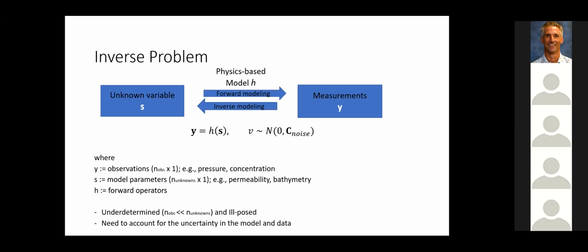And the data itself, the gauges have some observation error and other kinds of errors, and you have to account for uncertainty. So in the statistical, or stochastic, inverse problem, you have to provide not only the best estimate of the state S, but also the range of S, or uncertainty of S, in the final outputs or report.